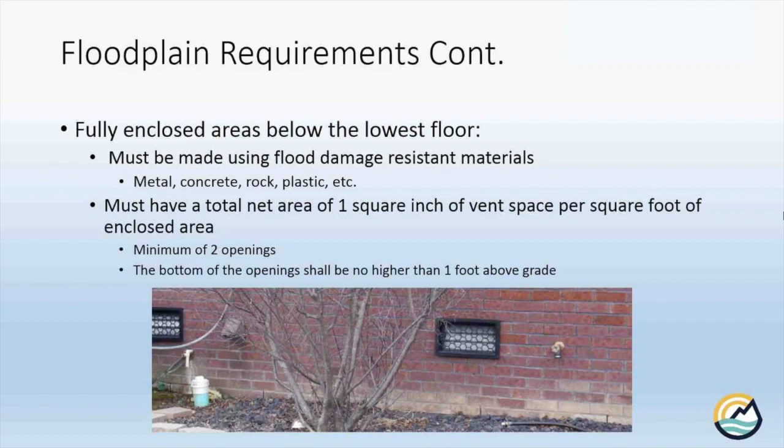The other thing they're looking at below that flood elevation is that any enclosed areas below the lowest floor have to be vented. The reason this is done is because water has a lot of pressure. Water's heavy. And so when you have water on one side of the wall and not the other, it is pushing very hard trying to get in that enclosed space. So when you have water getting up, you can have things like cracks in your foundation or collapsed foundation walls that can cause damage. So these vents actually equalize that pressure.